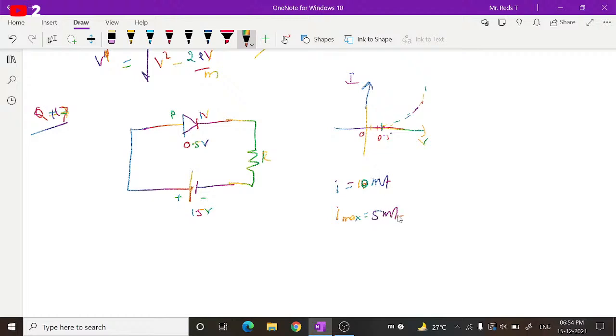What you have to understand here is that because its potential is 0.5 volts, when you connect to a battery, even though its potential is 1.5 volts, until 0.5 volt is reached there will be no current. That means 0.5 volts will be wasted in overcoming this. Then how much potential will be used to draw the current here?